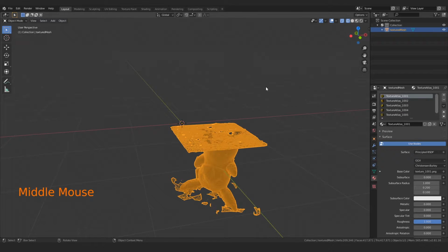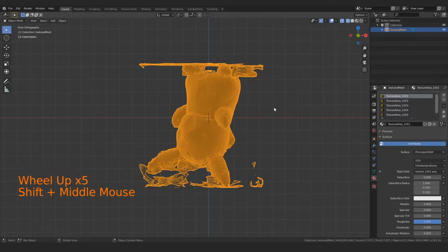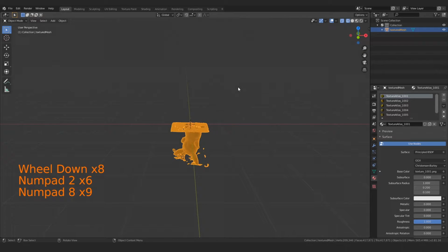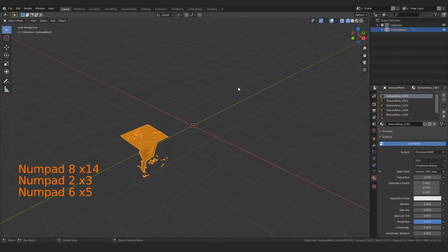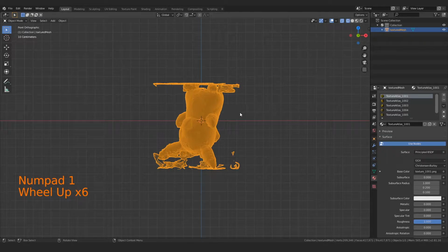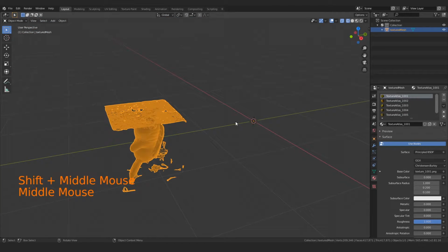And so I want the front view, so I'm going to hit 1 on the number pad so I can look at this from the front. The even keys, which I glossed over, are just going to nudge you in one direction or another. If I press the 2 key, it's going to nudge us down. If I press the 8 key, it's going to nudge us up, 6 will nudge us to the right, and 4 will nudge us to the left. So that's really what those even number keys are for. Actually, I can tumble out because we need to fix this whole placement location now that I'm done with my view rant.